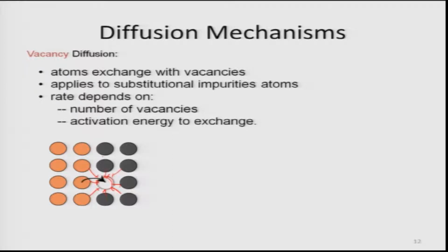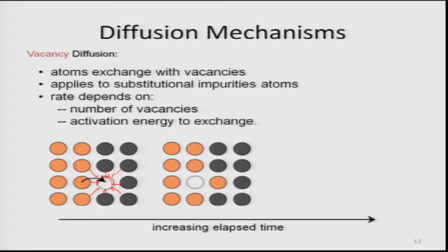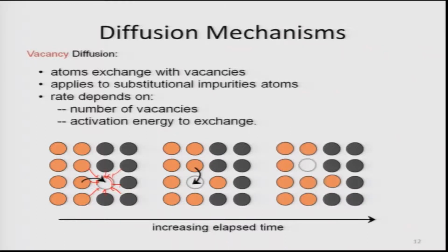Now, we can also see that these are the diffusions happening, as this black arrow shows, the atom has diffused from here to there. So, the vacancy has moved also. If the vacancy moves, then another atom can move into the vacancy. So, another configuration of atoms will happen, the vacancy has moved above. So, basically diffusion can also be treated as a movement of vacancies, with vacancies moving from here to there, and in the process atoms are also interchanging their positions.